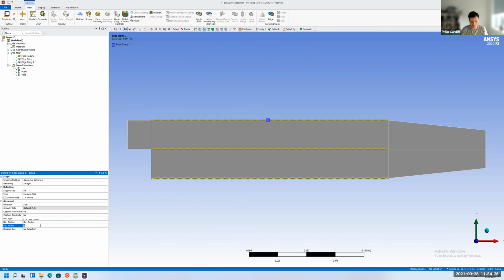So our factor will be 5, center. If you see here, the bottom one is the correct direction. It goes from small to big, but the other 2 are flipped. It's in the wrong way. So to reverse that bias or to flip it, just click on this last one here, and then left click on the first line, and then control click on the second one. And I just press apply and that will flip those. So you can see all three now are small on the left, big on the right.